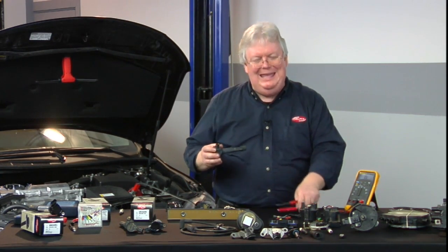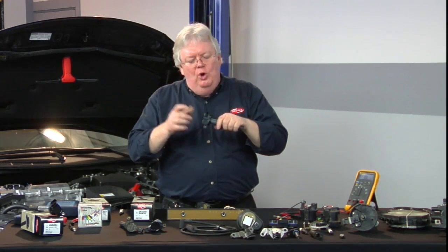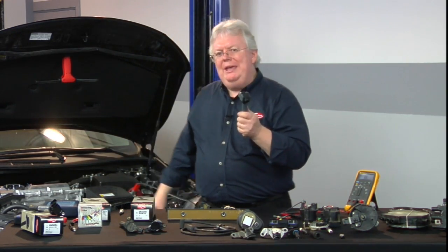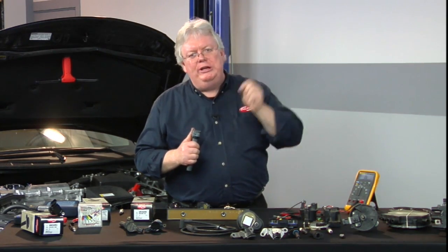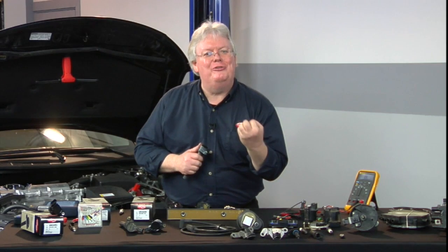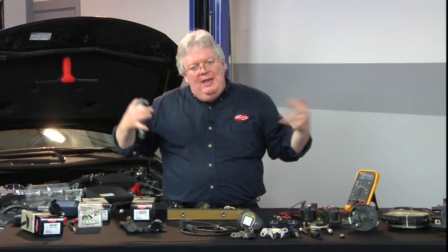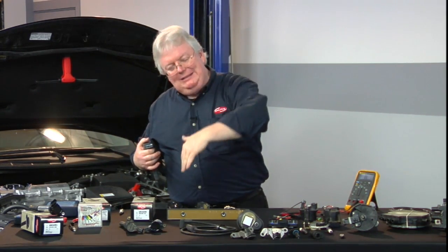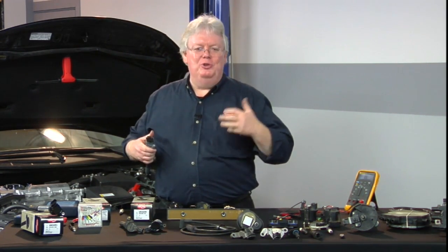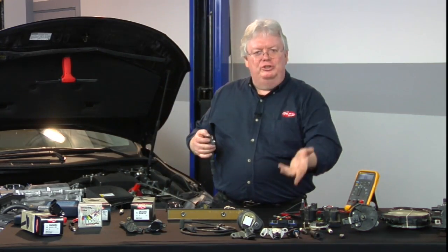I'm not measuring anything when it comes to the continuity of the secondary or the continuity of the primary. That's why we have to do the on-car testing, looking at the pattern of the trigger, triggering this thing, looking at the current draw of the coil. If the coil is not building up a field and then turning that off, and we don't see that ramp up with an amp clamp and then back down, then it's not working. And so that's the modern way of checking the coil out as opposed to just using the ohmmeter like we used to do.